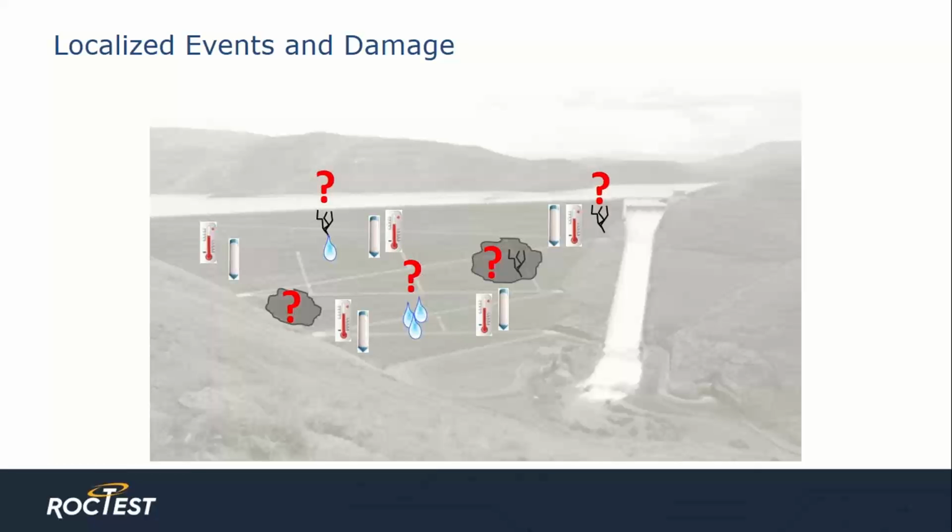One of the downsides to using traditional sensing is the single point nature of the sensors themselves, requiring a lot of guesswork as to what's happening between the sensor locations. In this graphic, you can see the large physical distance between monitoring locations. Another downside to this method is cost. Adequate evaluation of a large structure, such as a dam, requires an extremely large amount of sensors to be installed on the structure, making cost a primary concern for both materials and installation.